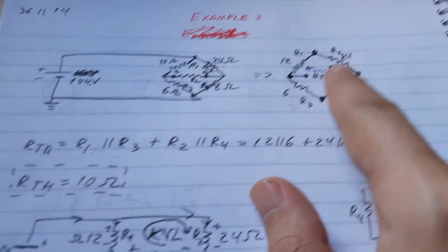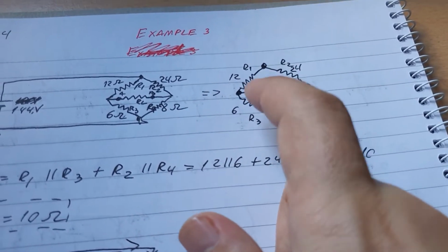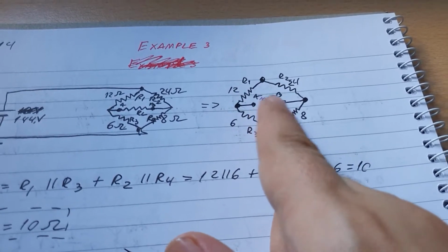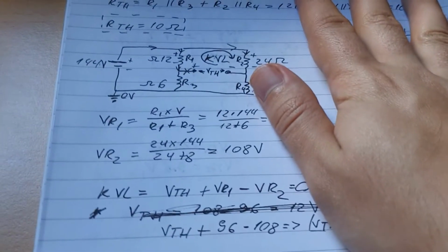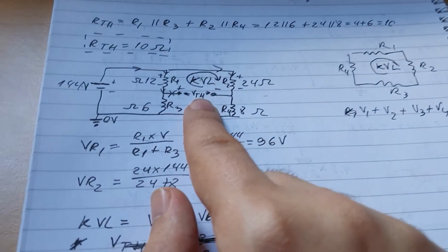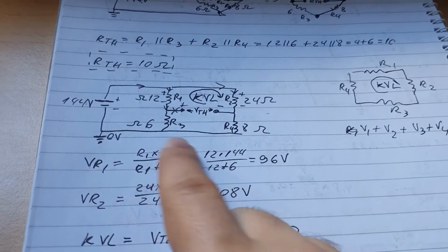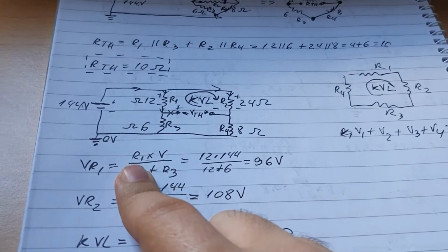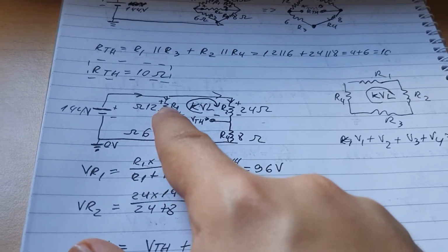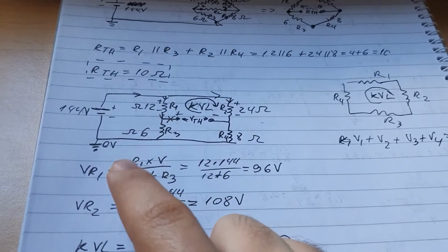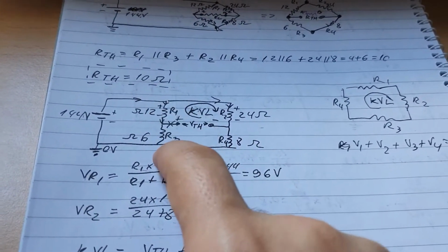Again, here we got 10 ohms and we calculate them as parallel because this is a short circuit. We see it as a short circuit. However, in here we see it as an open circuit because there's no current going through it. So we managed to use this formula here to calculate it, which is basically the resistance, the current going through R1 divided by the total series resistance between those two, between the ground and the top.